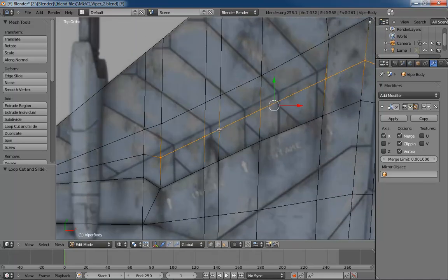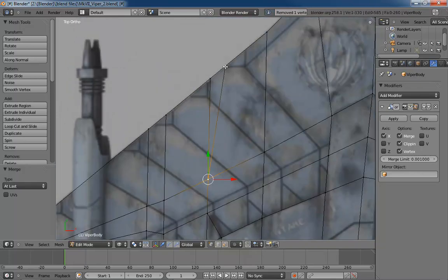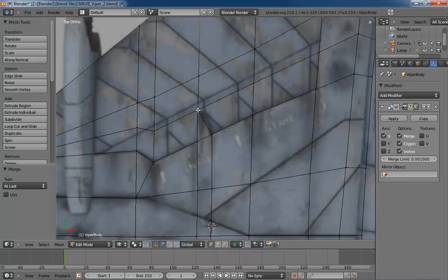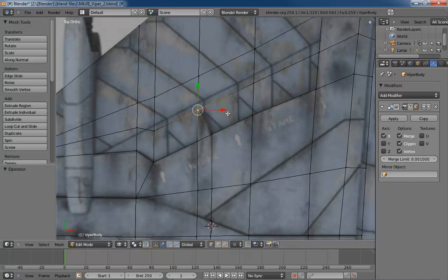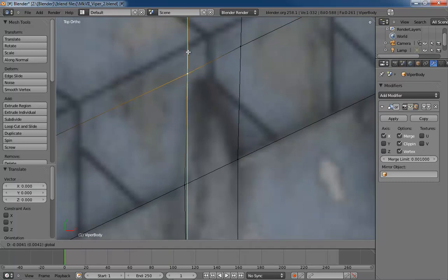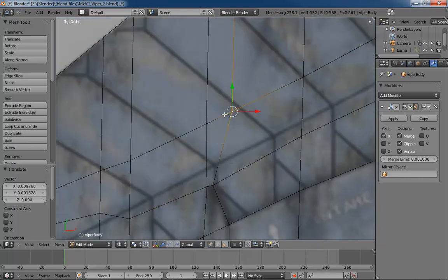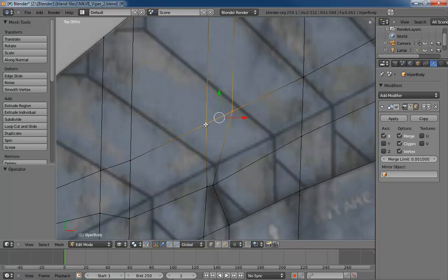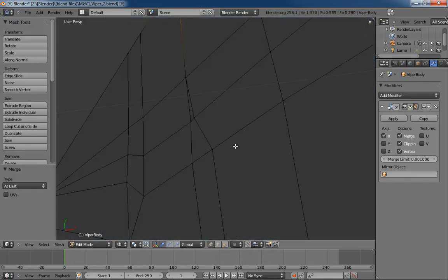Now, let's switch over to vertices, and Alt-M, merge these together, Shift-R, Shift-R. Now we can take this and center it up. I just don't know about making that a single point. I think that's what's bothering me, is that I would like that to have just a little bit of thickness when it's done, because it's not really a point. It's got a little bit of rounding. I understand that adding that much rounding could be problematic for us. At the same time, just leaving a little bit of a straight edge there at the tip is going to help a lot. So maybe what we can do is hit our merges from here up, and just let that go for now.